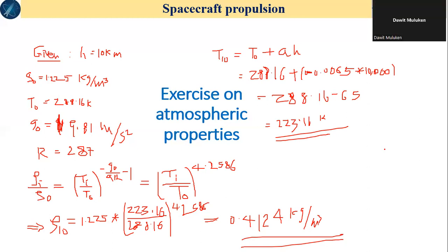Okay. So this summarizes a formula we developed: geopotential altitude equals R times Hg over R plus Hg. So what is given here is Hg, and R, the radius of earth, is known. So you need to find H. Work this out too and show me. So I think this is sufficient for today.